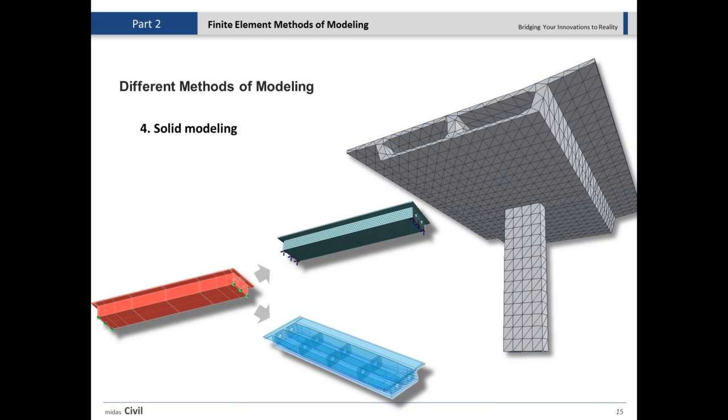Because in post-tension bridges, sometimes you need to study a certain part of the structure in great detail. For example, you may need to study the anchor blocks, or other effects. You can model a certain part of the structure or the complete bridge in FEA, define the linear and non-linear material properties, the time-dependent material properties which are non-linear, and also all the tendons. It could be modeled as a plate or solid, and then you can post-tension them easily and get the final